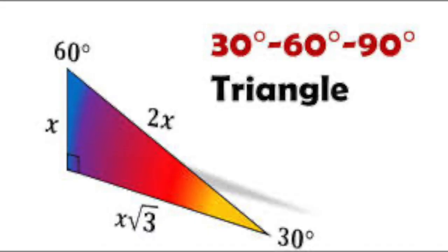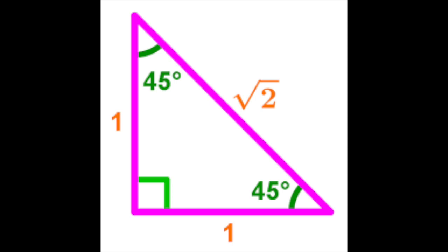There's triangles behind the scenes in everything that you're doing, even if you know it or not. When you're bending conduit, the distance that you put between your two lines when you're bending an offset, if you're using 30-degree bends, you're using the laws of a 30, 60, 90 triangle. And you use a multiplier of 2 because 2 is the hypotenuse of a 30, 60, 90 triangle. And if you're bending an offset using 45-degree bends, you're using a 45, 45, 90 invisible triangle that's behind the scenes. And in a 45, 45, 90 triangle, you're using the square root of 2, which is 1.414.